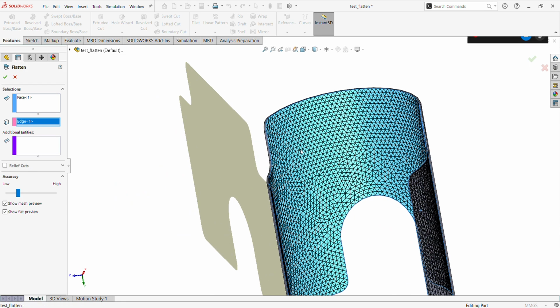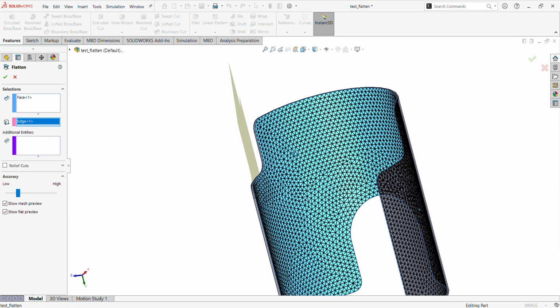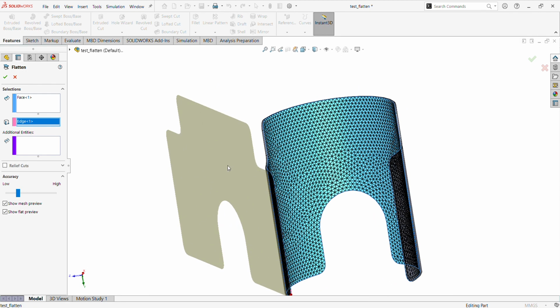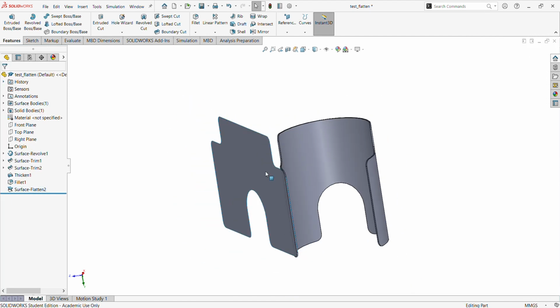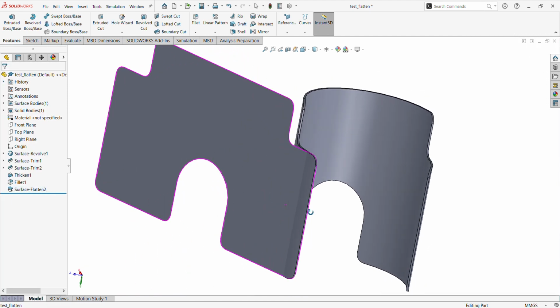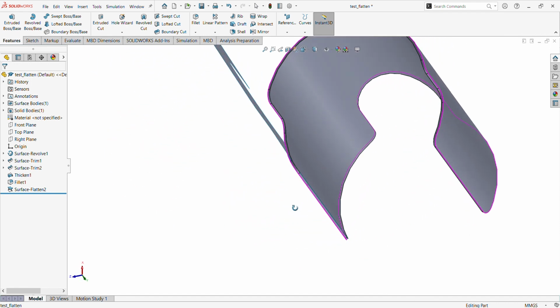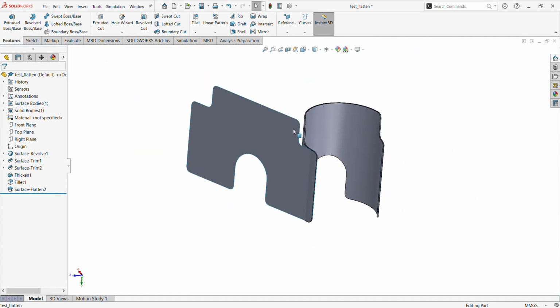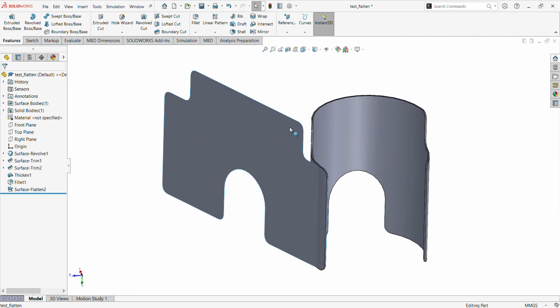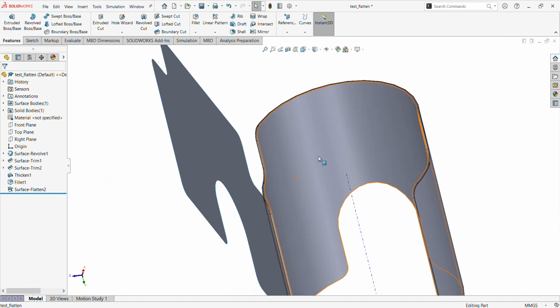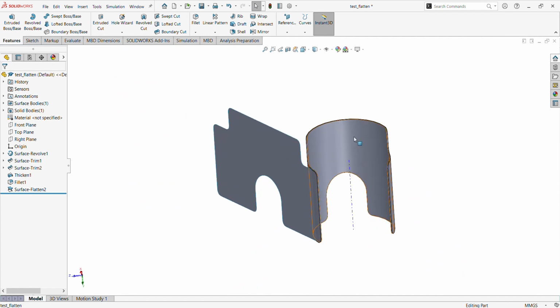It produces a mesh of the solid, and is able to flatten the solid. So if we say approved, we can see the flat part of the solid. This also enables us to test at every point in time whether our surface modeling, in case we are working with sheet metal, will be able to be flattened in the sheet metal.